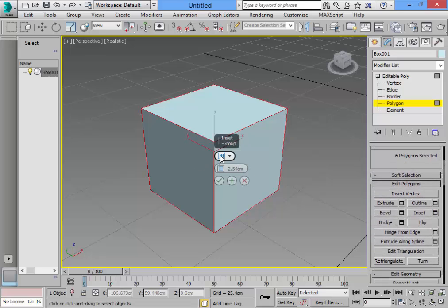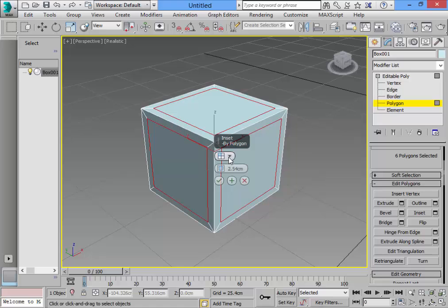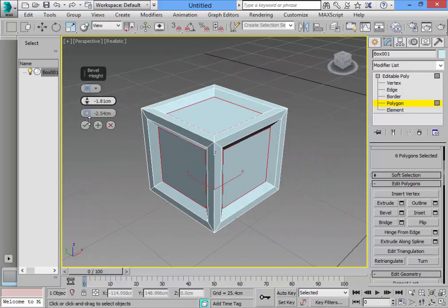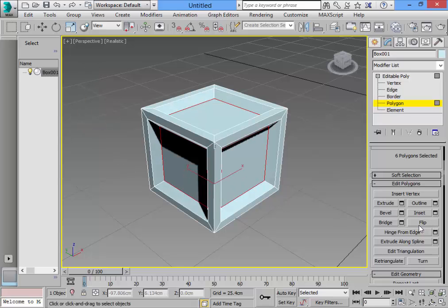But while I'm insetting, I'm going to inset every polygon by itself. Okay, I just made smaller boxes. That's good. Once I made this, I'm just going to make those polygons have a bevel. It will be pushed towards the inside. Okay, I'm just going to make a bevel, and I'm going to push them towards the inside. Okay, let it be something like this. A good cube structure.